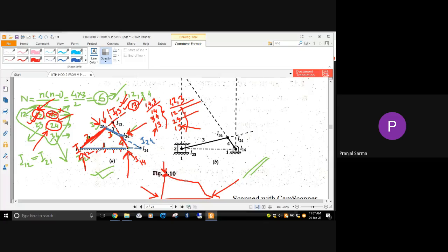We draw these diagrams as per some scale, and the scale will be mentioned while drawing the configuration diagram itself. Later, if you measure the distances of the points from a particular instantaneous center, then you can have the conversion. Similarly, that relationship you can utilize and find out the velocities of different points. That is how we utilize the concept of instantaneous center for finding out velocities in mechanisms.